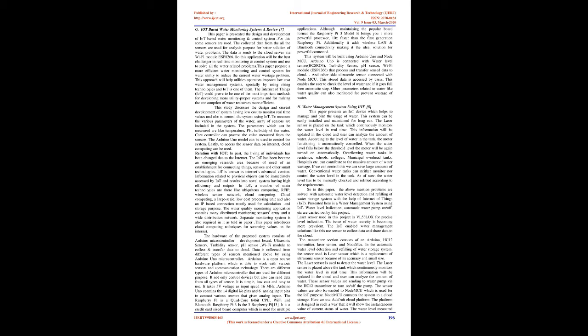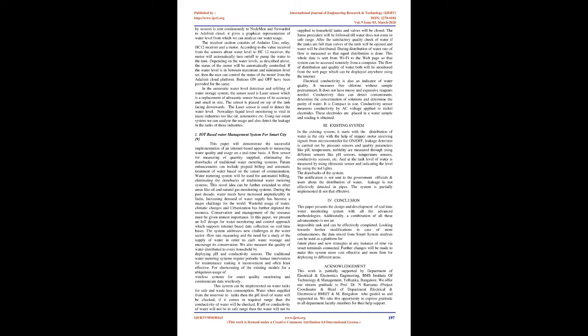The hardware of the proposed system consists of an Arduino microcontroller development board, ultrasonic sensors, turbidity sensor, pH sensor, and Wi-Fi module to collect and transfer data to the cloud. Data is collected from the different types of sensors mentioned above by using an Arduino Uno microcontroller. Arduino is an open-source hardware platform which is able to work with various sensors and communication technology.